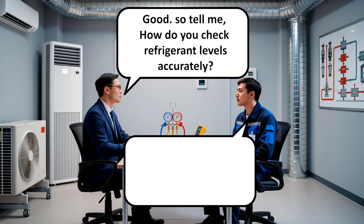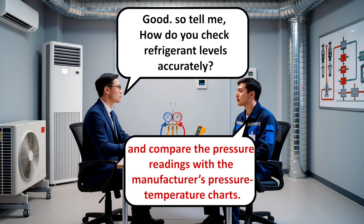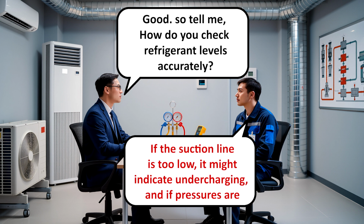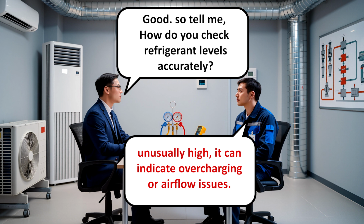Good. So tell me, how do you check refrigerant levels accurately? So to check refrigerant levels properly, I always use a manifold gauge set and compare the pressure readings with the manufacturer's pressure temperature charts. If the suction line is too low, it might indicate undercharging. And if pressures are unusually high, it can indicate overcharging or airflow issues.